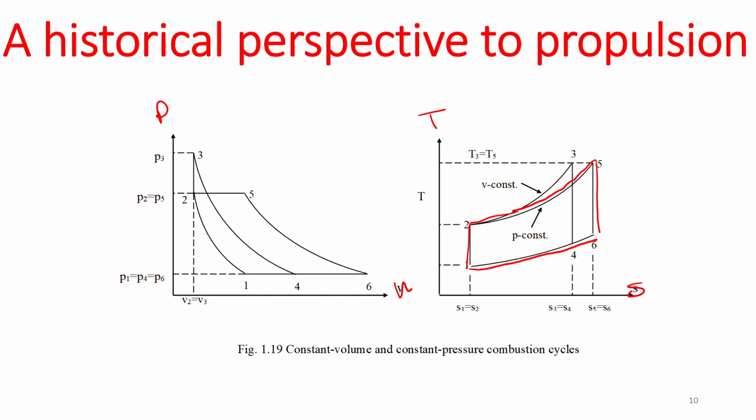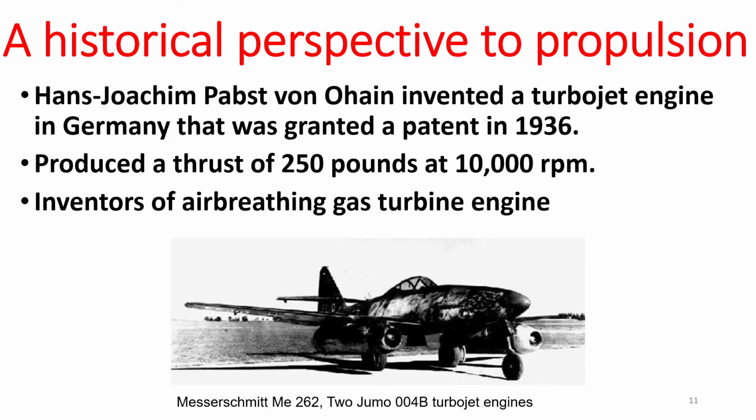And on the PV diagram, as you can see, we still have your Brayton cycle, with constant pressure and constant entropy processes. We can do a lot of calculations. If we have these TS diagrams, we can do the thermal efficiency calculations, which we'll discuss later in this lecture.